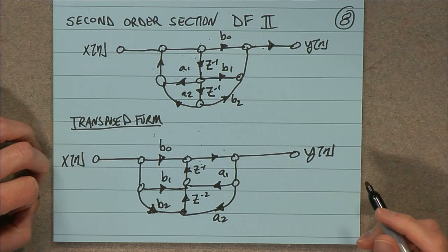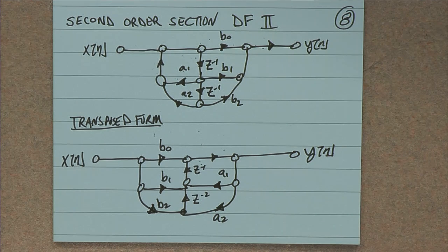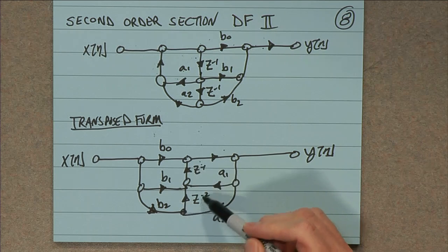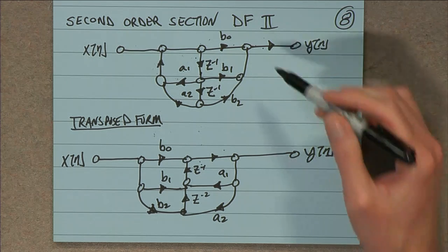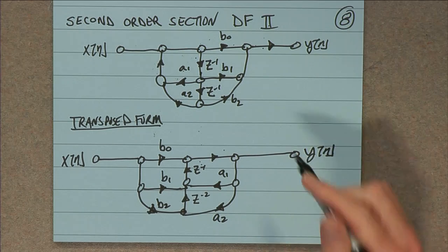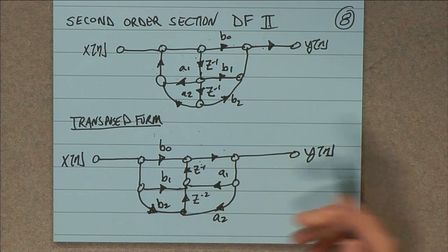If you recall back at the very beginning last time, we talked about, okay, what's one way we can manipulate these forms? And we had direct form 1. Direct form 1 actually did the B coefficients first and then finally did the A coefficients. But it required, if you recall, 2 sets of delay networks. So it required twice as many delay elements as the direct form 2. Now you can see maybe the utility of this is that you can implement the B coefficients first if you'd like and still use this more efficient form.